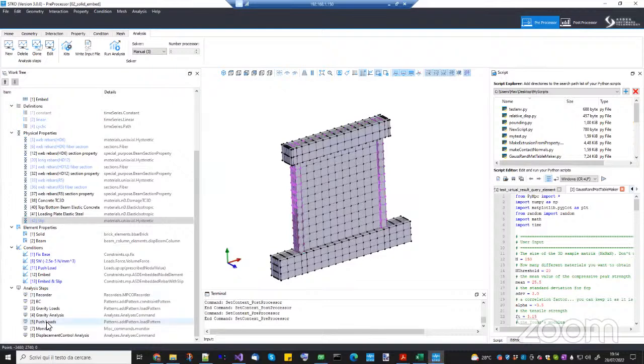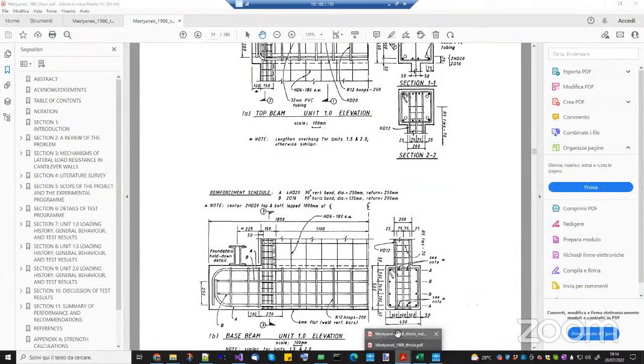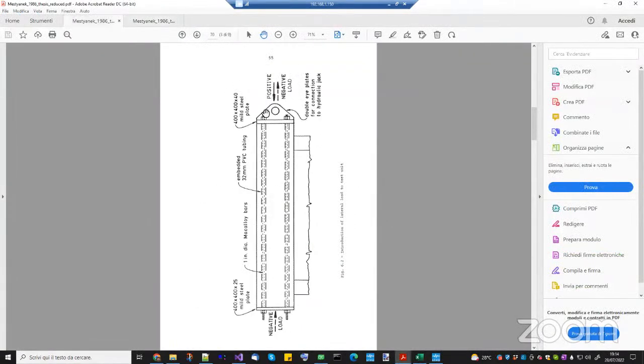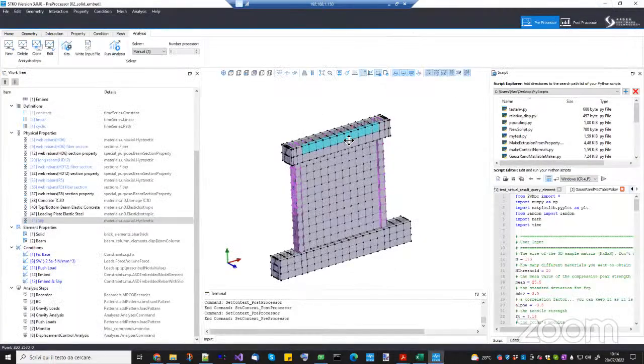So another solution that is very fast is to use contact elements. So you can use actually a physically based approach. So what they do here is to basically push and pull this side. Then this side is rigidly linked to the other side, so that when I pull this one, here I will have separation, so no traction because there is no contact when it is separating. But through the contact, it will apply a push on this side, okay? So let's try to see how it can be done.